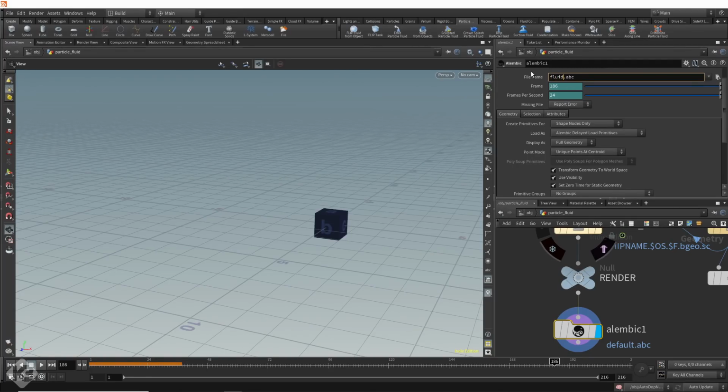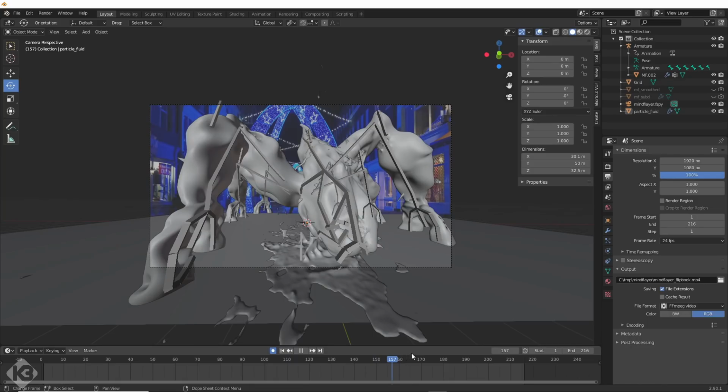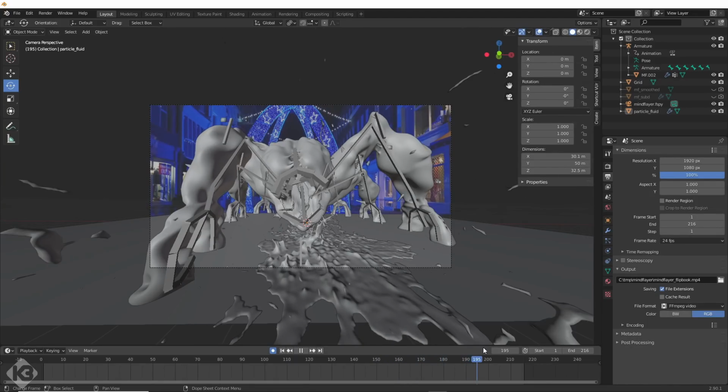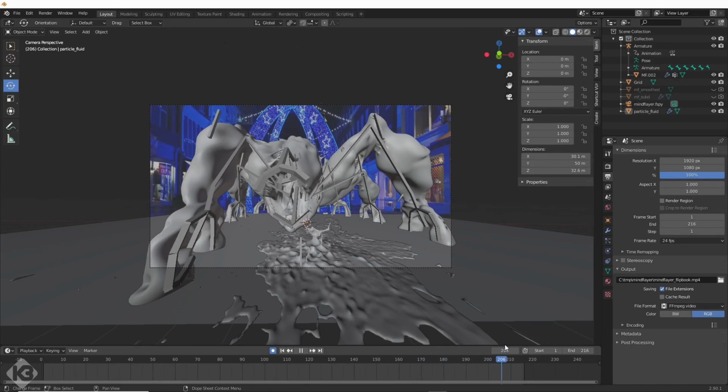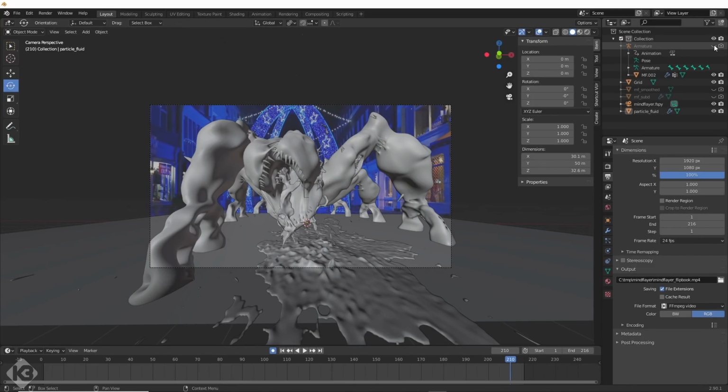I could have done a flipbook in Houdini, but I wanted to see if this would even come into Blender. It did. I did some tests and shaded it. It looked decent, but I wanted to further refine it. So I went back and forth like 5 times until I got the fluid looking okay. It turned out that I needed the simulation to run at double speed, probably due to the scene scale that I didn't set in the beginning of the Houdini session.